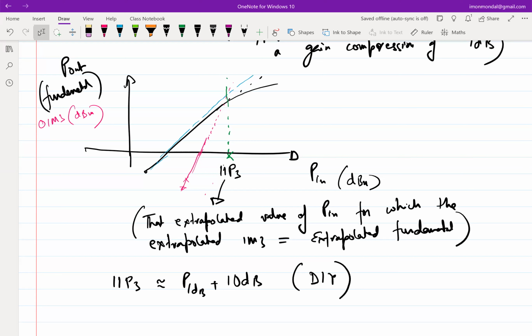Yes, it's basically the biasing, right? The sign of the coefficient depends on where you bias. The Taylor series is totally based on the derivative of the curves around the operating point. An operating point is where you bias. You plot ID versus VGS, you take your differential around the operating point, and you get a bunch of terms. From those terms, you will know whether it's going to expand or compress, based on whether that term becomes dominant or not. And that will give you the idea.